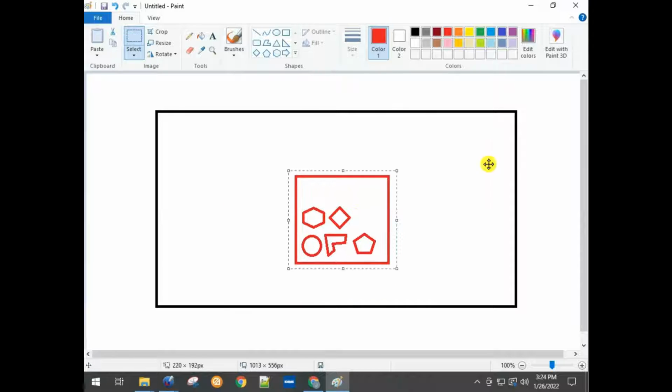Then we jog our cutting head over to the corner, put it on the corner, and start cutting from there. So that would be a G92 program. Again, all of those XYZ coordinates are based off of wherever the cutting head is when you start your program.